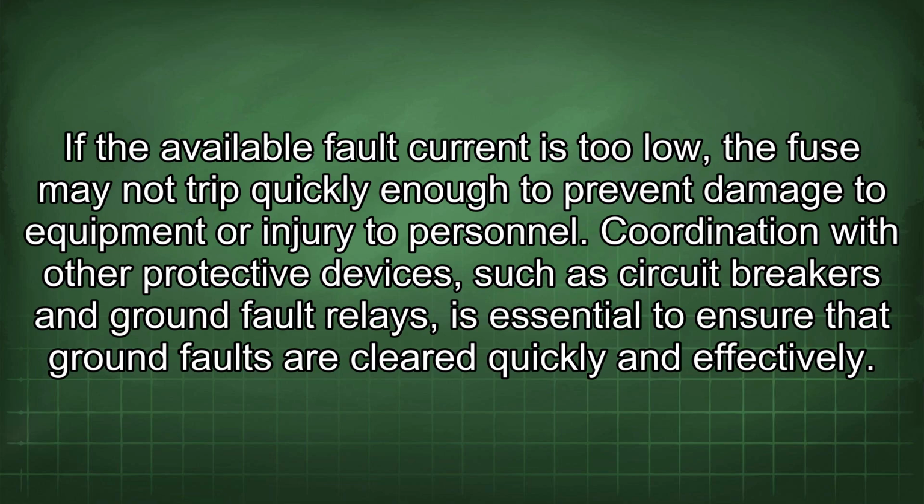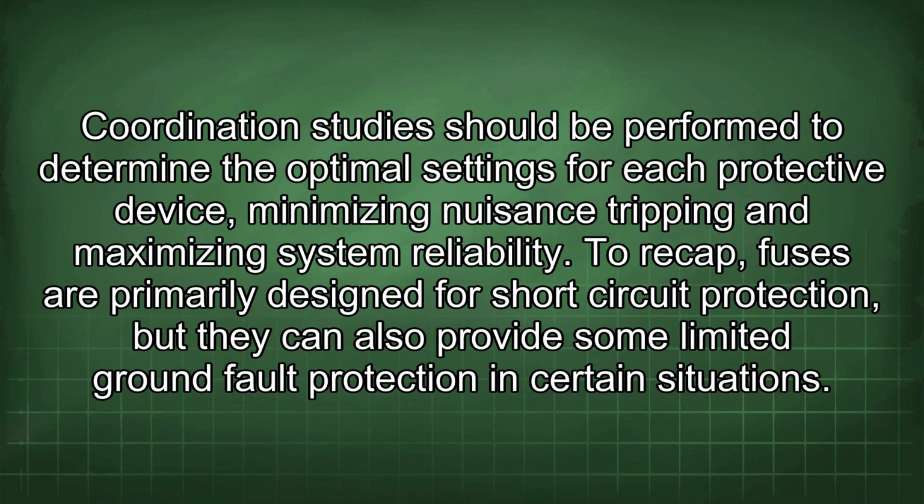Coordination with other protective devices, such as circuit breakers and ground fault relays, is essential to ensure that ground faults are cleared quickly and effectively. Coordination studies should be performed to determine the optimal settings for each protective device, minimizing nuisance tripping and maximizing system reliability. To recap, fuses are primarily designed for short-circuit protection, but they can also provide some limited ground fault protection